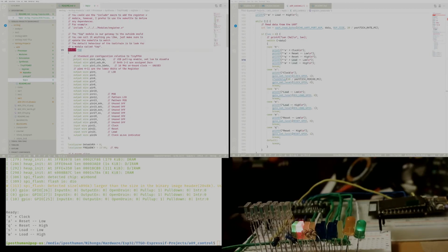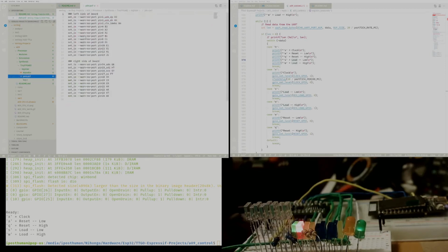And it almost always defines your pins to the outside world. And here are all the pins that I'm either using or turning off. These pins are defined in a pin constraint file, which we have here. And this I downloaded from the Tiny FPGA website. And then you go through and you turn on all the pins that you want to use.